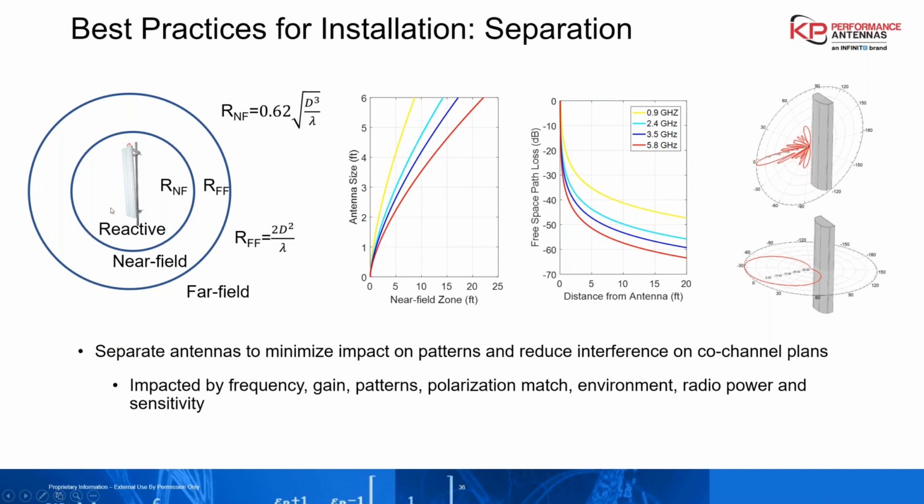The antenna type, are they on the same frequencies? If you're on the same frequency, you've got to have a lot of separation. 5 feet separation if you're doing back-to-back, or more if you can. Now, if they're not on the same frequency, so they're on different channels, you don't have to worry about interference that much between the two, as opposed to when on the same frequency.